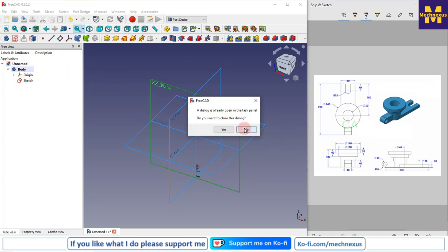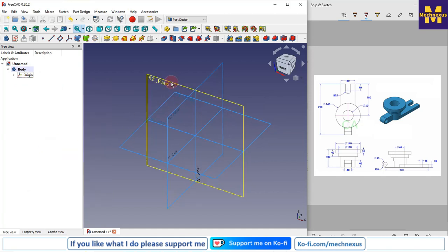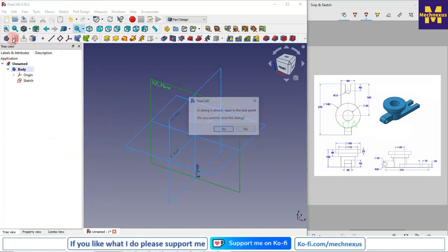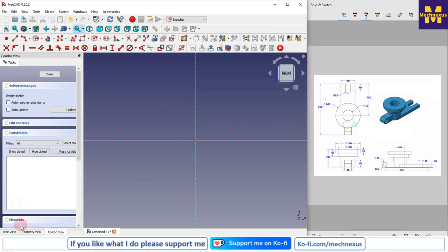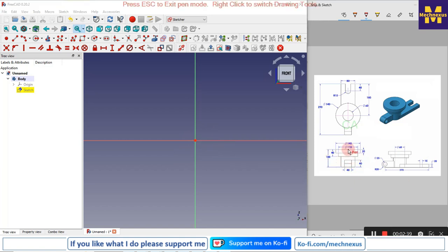Here the sketch already exists, so I will delete it. I will select this plane and create a sketch, and I will turn off my origin plane, and now I will create the revolve feature. For the revolve feature I will create my profile from the center line.